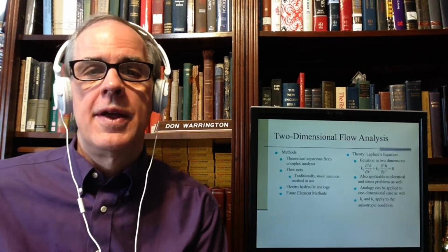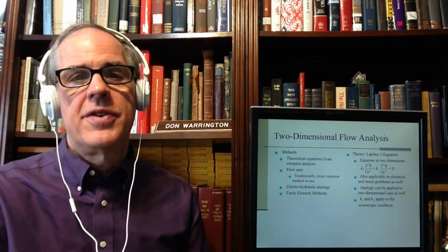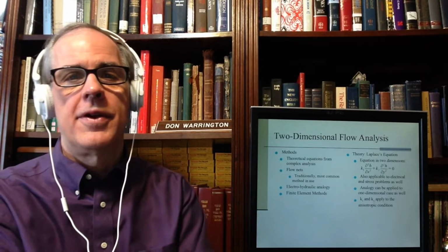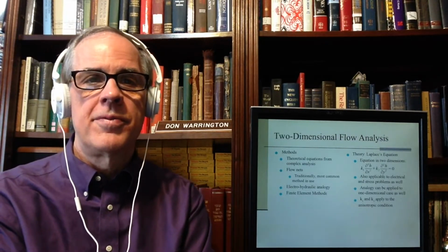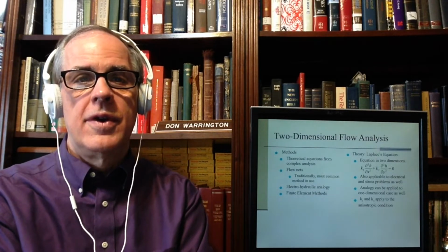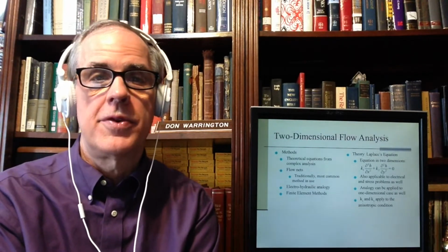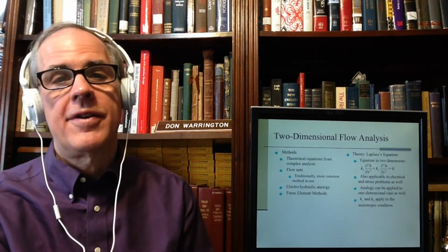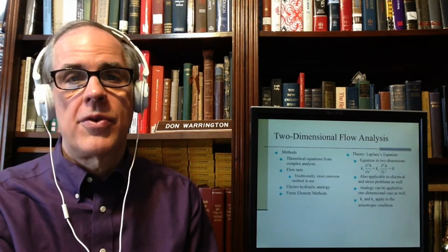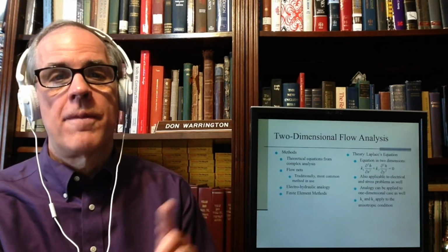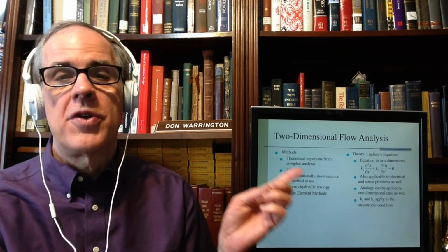One interesting aspect from a fluid dynamics is that we have a lot of different... if you all remember fluid mechanics, we talked about the Navier-Stokes equations, and they're not easy to solve. It's done now with computational fluid dynamics and that sort of thing. And then if you take the viscosity out of those equations, you get Euler's equations. And then if you keep simplifying it down, really the simplest form, this assumes it's laminar, irrotational.